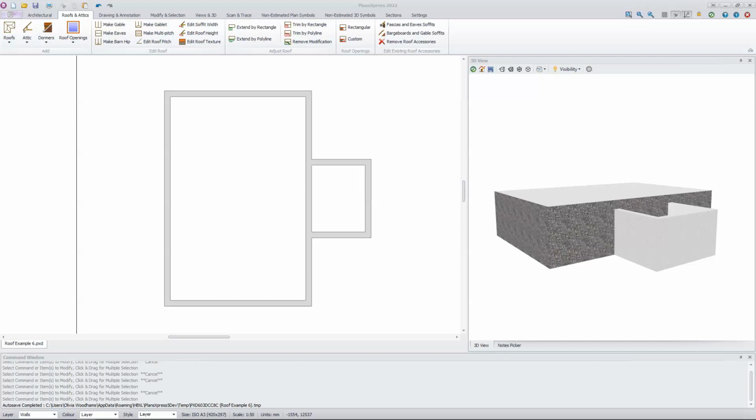2,325mm. If I used the hipped roof option and drew the entire roof using the one-click method, the software would automatically draw the roof at one level. Therefore, I need to draw the two sections of roof separately using the rectangular method. I'm going to start by drawing the hipped main roof and then add the apex valley roof.